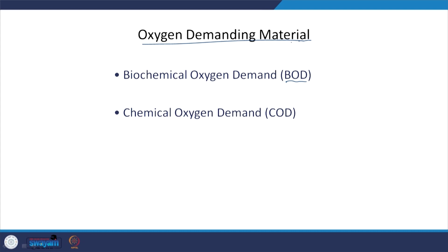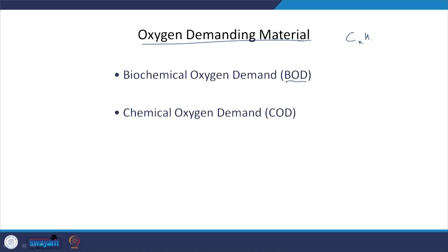And what is the oxygen demanding material? Typically it is waste or industrial waste which are reduced compounds. You see it is relatively reduced out here, we have the H out here, right, and if it is completely oxidized, it would go to carbon dioxide. Here it is relatively oxidized, here relatively reduced. So, how will they go from here to here? They will need oxygen to go from here to here, right, and that is why we are calling these compounds oxygen demanding material, and we are using variables such as BOD or COD to try to approximate this oxygen demanding material.